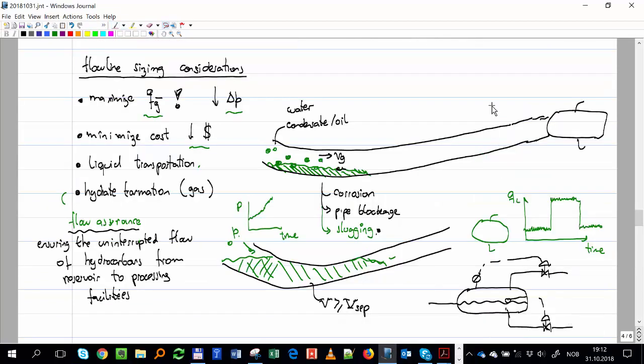It's not so simple as to just increase rate and that's all. Okay, reduce pressure drop. There are a bunch of all other things we have to take into account. Flow assurance is a big part of it. I hope last year we did an exercise on wax. Okay, it's a bit easier to calculate temperature drop in liquid than in gas.